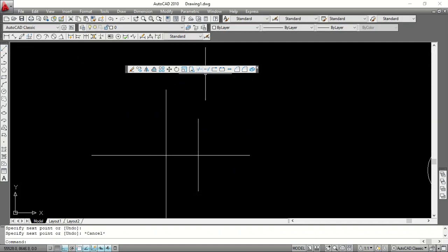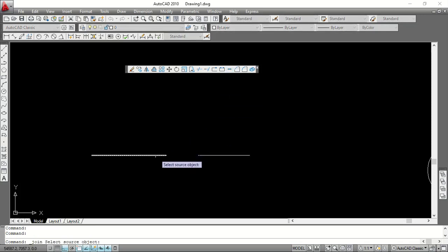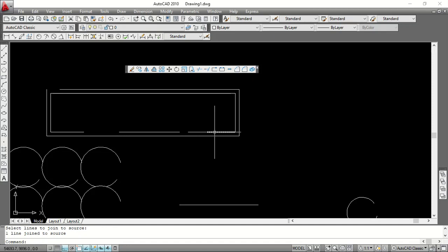All right, so I pick the trim tool. Where is it? Pick. I trim this. Okay. Now I want to join these two lines together. So I click this, click on the first line, click on the second line, right click so it joins. So why this one is not joining is because they are polylines. So their behaviors are different.